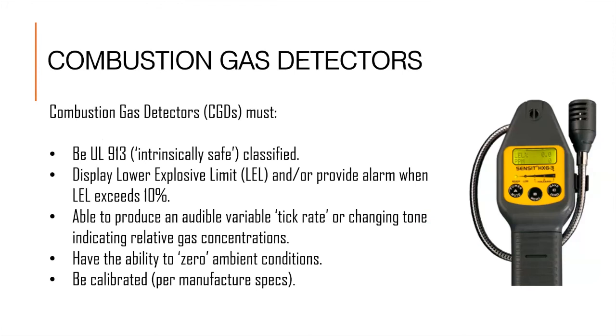Combustion gas detectors, often referred to as gas sniffers, have to meet the following criteria. They need to be intrinsically safe. What that means is that they don't have sparks in their electronics that could potentially ignite in a combustible environment. They also have to display a lower explosive limit and provide an alarm if that atmospheric level exceeds 10%.